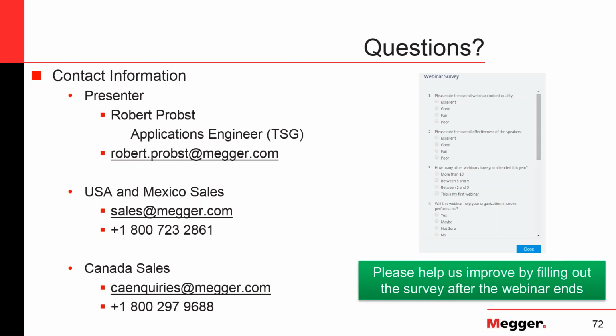No, this is a typical offline test. So you do not do that injection while the equipment is energized. This is a test that you do as part of your maintenance approach, of your maintenance program. So you take a substation, a feeder, whatever, out of service, and then when it's de-energized, you inject the current through the test device.